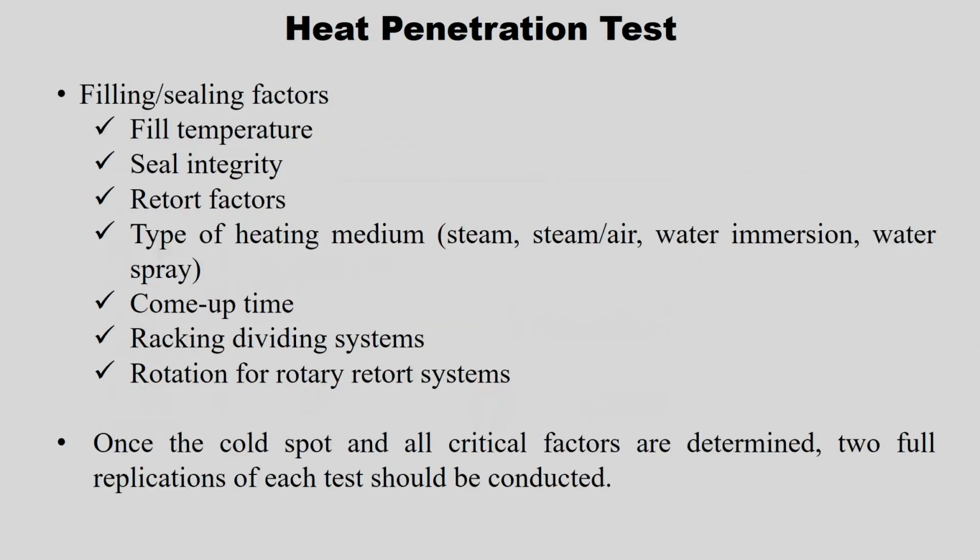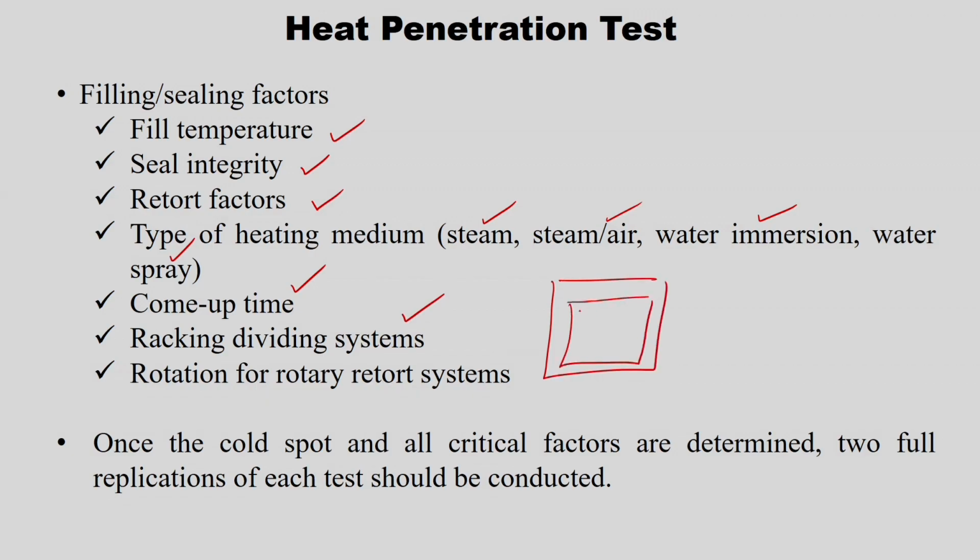Then the filling and sealing factors: fill temperature, seal integrity and retort factors, and the type of heating medium used, whether it is steam, air or steam-air combination, or water immersion or water spray technique, which type of heating medium I am using. Then the come-up time, so how long it takes to reach the exact heating medium temperature. Then the racking or dividing system, in the sense that I have a retort and here I have a crate. So, in this my containers are stacked. So, also the gap between the 2 containers when I insert the thermocouple. So, everything has to be taken into account while doing the heat penetration test.